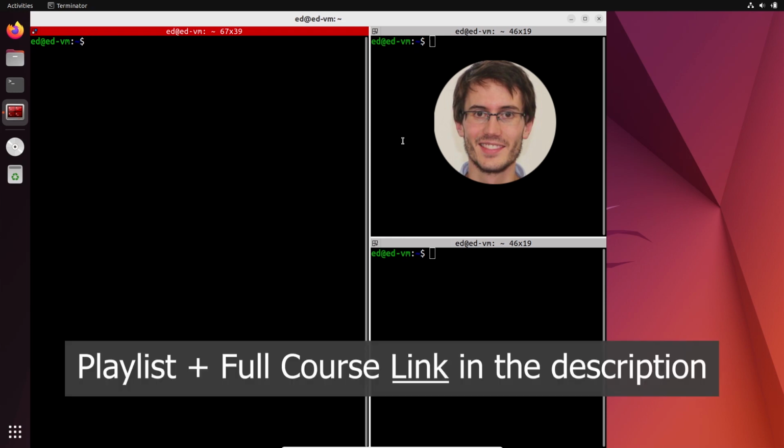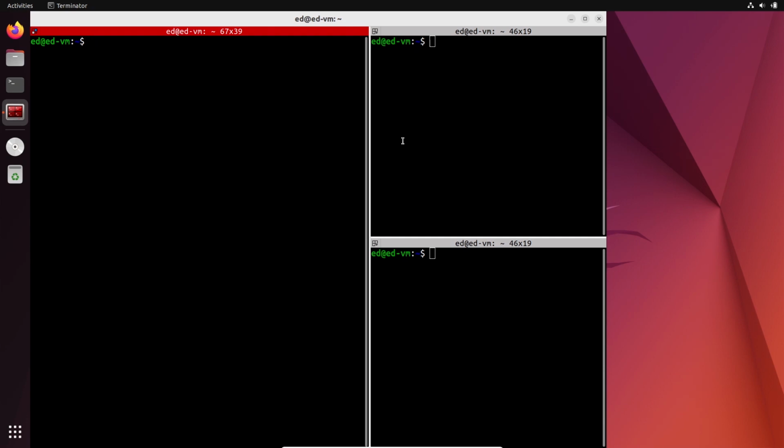Let's get started. As for now, in this tutorial series, we have created one publisher in one node and one subscriber in another node. But we can do better than that. We can create one node which is going to contain both a subscriber and a publisher. And in this particular case with the turtlesim, what we are going to do is to create a closed loop system for the turtle.